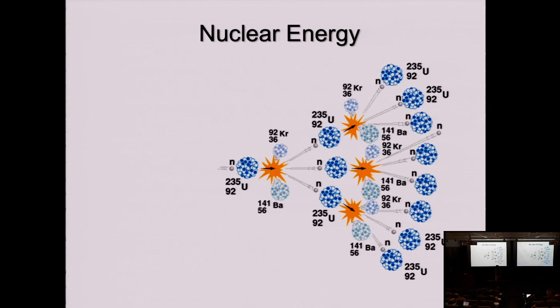Including an economic discussion of the fact that of the 3 traditional solar photovoltaics that we use, there's monocrystalline, there's polycrystalline, there's amorphous, and it's an interesting economic situation where monocrystalline are the most expensive to make, but they are the most efficient. On the other end, you have amorphous, which is the least expensive to make, essentially slosh some silica, molten silica, into a pan and let it dry. Those are the least expensive to make, but they're the least efficient, approaching something like 4%. And so you have to make these economic decisions